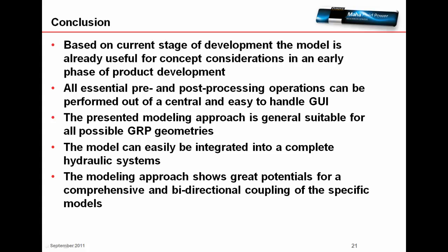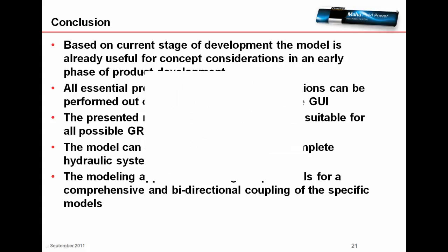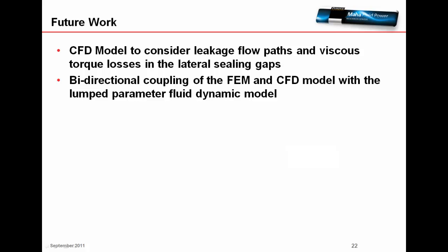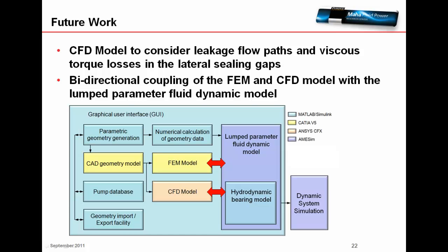And this brings me to our future activities. We will continue working on the CFD model to accurately consider leakage flow paths and viscous torque losses in the lateral sealing gaps between the two gears and the housing. This will be presented at the AFK Symposium in Dresden, Germany, next year. And we will also continue working on the coupling of the 3D models with the lumped parameter fluid dynamic model.